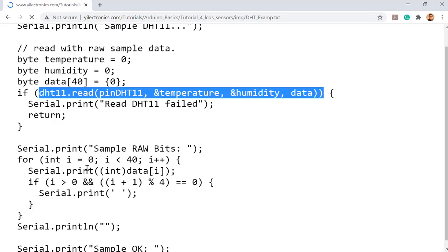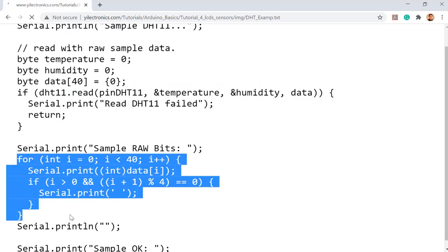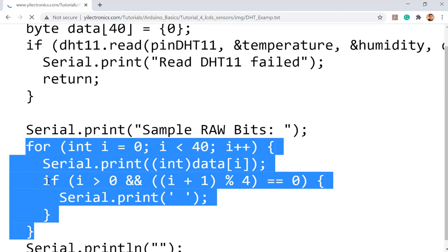Okay, so now here's a for loop to do this job. Just do a loop with an index starting from 0 to 40, so you can scan all the binary data in the array. Every time, you find the data at that location and print it. Because the digital system can run really quickly, you can display all the digits in the serial monitor really quickly as one piece of data, right?